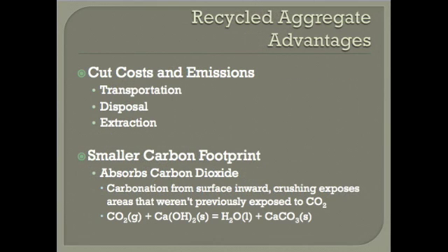If there weren't any advantages, then recycled aggregates wouldn't be used. These aggregates cut costs in a variety of ways. They cut the transportation and extraction cost of mining and moving traditional aggregates. They also cut the transportation and disposal costs to get rid of old concrete.